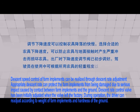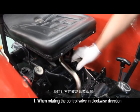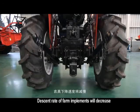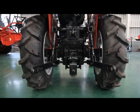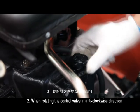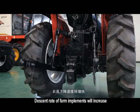During operation, the driver can readjust according to weight of farm implements and hardness of the ground. 1. When rotating the control valve in clockwise direction, descent rate of farm implements will decrease. 2. When rotating the control valve in anti-clockwise direction, descent rate of farm implements will increase.